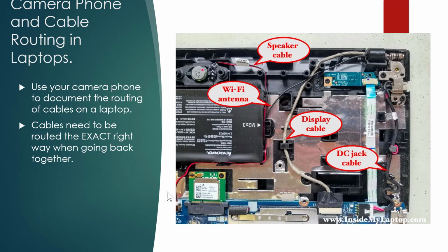So get organized, use a magnetic mat, get your service manuals, and take pictures as you work on these laptops. Work slowly and methodically. If you start to get frustrated, step away, come back later, go do more research online.